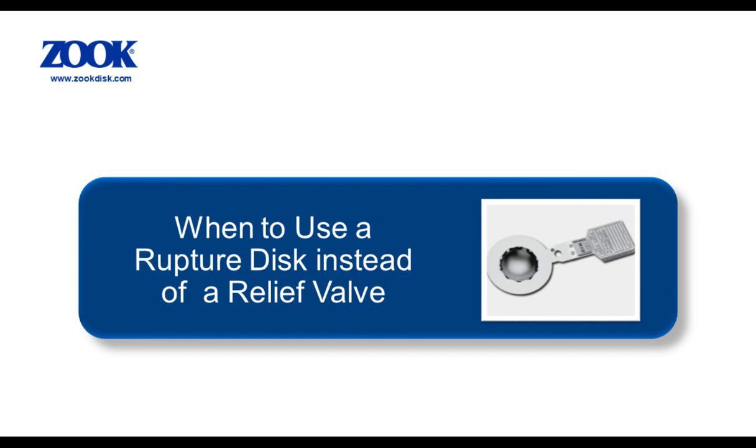There is another method of pressure relief that most of you will be aware of, and that is a pressure relief valve, also known as a safety relief valve. A safety relief valve is typically a reclosing device, so why use a rupture disc instead of a relief valve? Let's look at cost. Comparatively speaking, rupture discs are very inexpensive compared to valves, which have large housings and intricate mechanicals, especially in larger sizes or when exotic materials of construction are required.